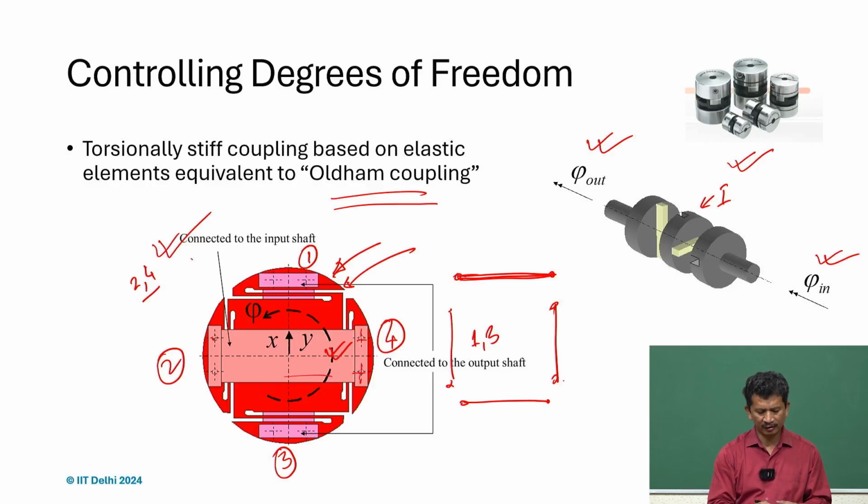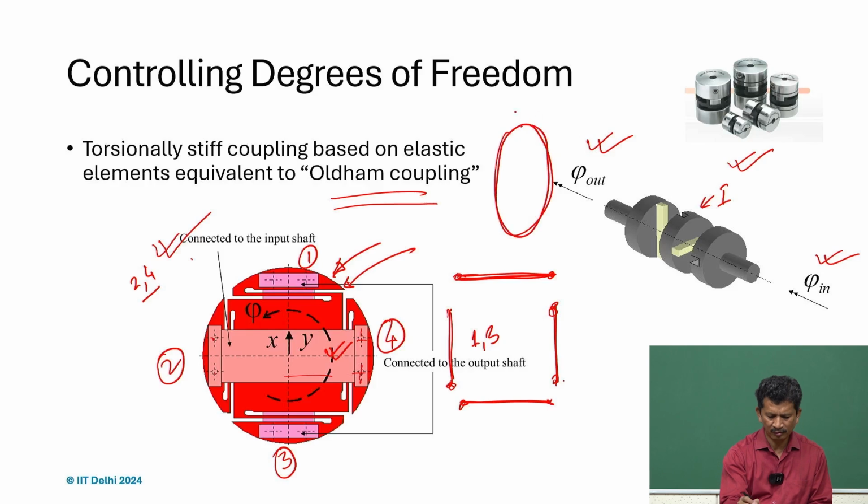So, the coupling here is just a thin plate. You just take a very thin plate and make this a structure. So, you just remove the material. Yeah, if you really want a very rough one, you can even use a saw and just make those slits. And what is important is this functional part in the center, a beam-like structure. So, suppose you can simply take a thin disc of very small thickness t, even a disc of thickness 0.5 millimeter should be sufficient to provide that constraint.